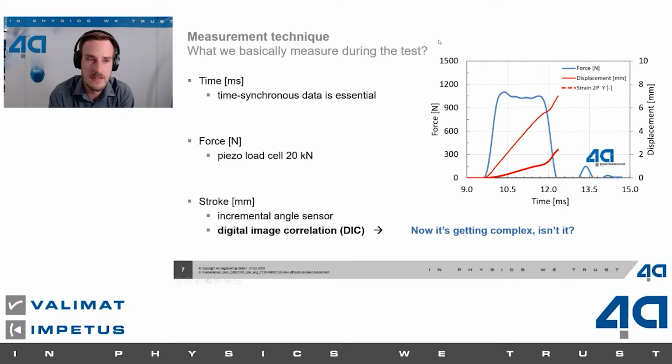Let us talk about the measurement technique of the tensile test. As you know, in the normal pendulum test, we are using acceleration sensors on the pendulum head to calculate the force. In this tensile test, it's a little bit different. In this test, we are using directly a piezo load cell with a full scale of 20 kilonewton. This is one channel that we are recording.